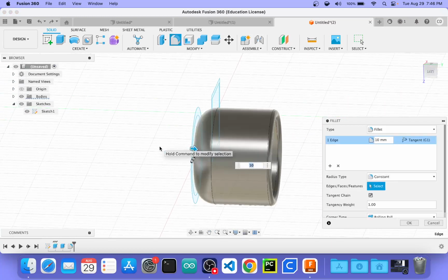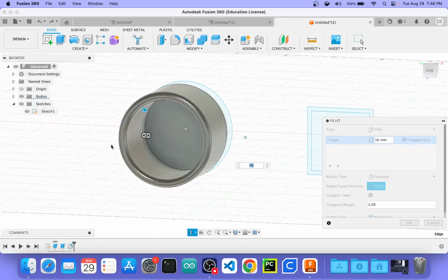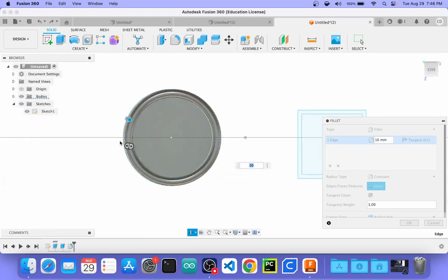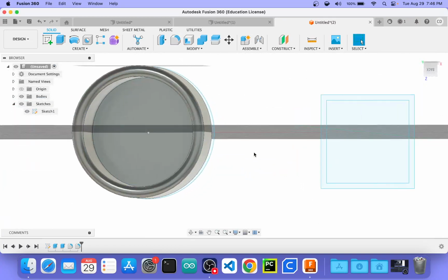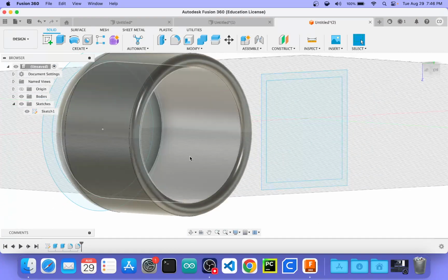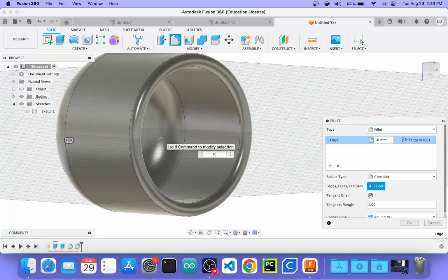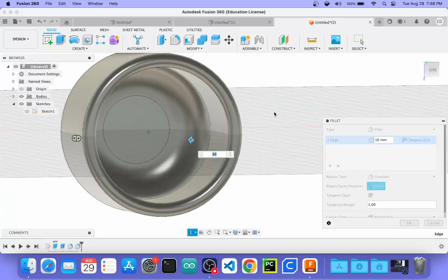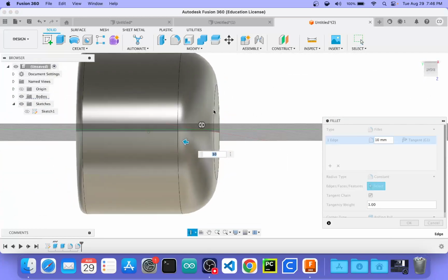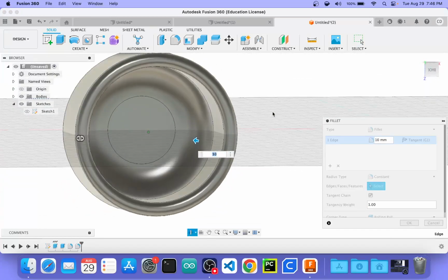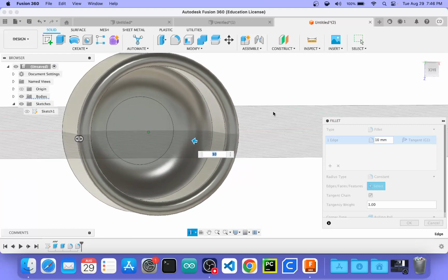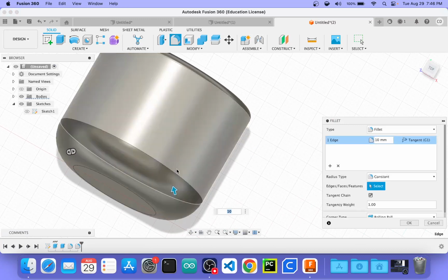So if you are working on a part that's going to have to withstand stresses, you might end up with a part that is unexpectedly weak in certain places. Now, something you can do if you've got a fillet like this to strengthen it is you can actually fillet the inside, and that is going to bring it in a little bit. So if I do a 10 millimeter fillet, that is going to match the interior and exterior surfaces, and it's actually going to give me a little bit more material down here.